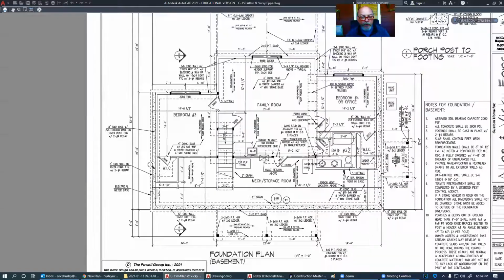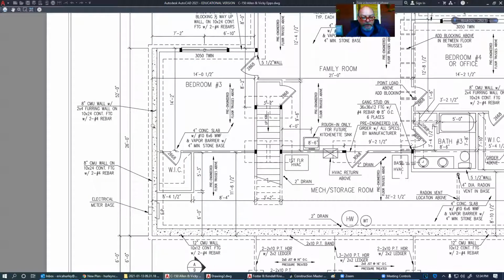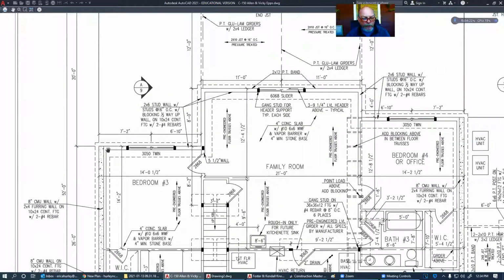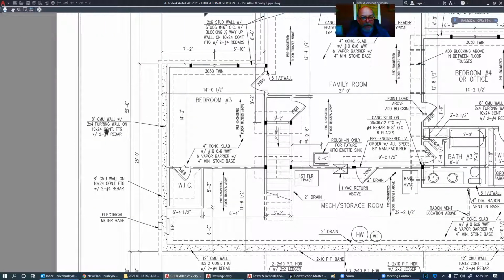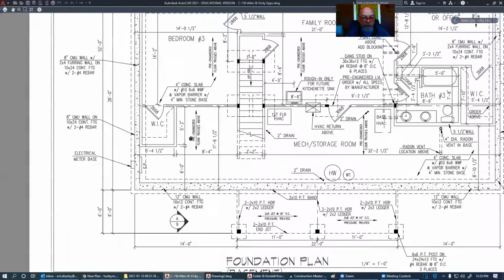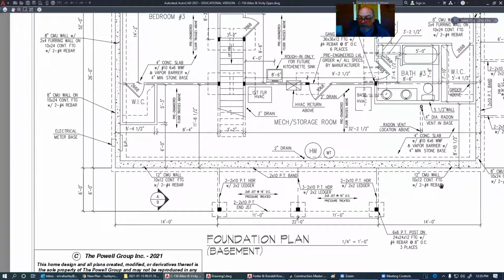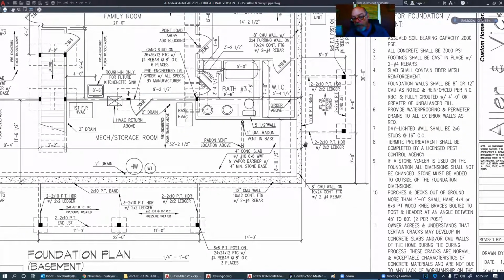Okay, so if we're looking at this drawing, we see that this is concrete across through here. But then look up here at the top. Now all of a sudden we've got these walls up here, these daylight walls. Well, there's a great big note that says we have 2x6 stud walls in here, as well as an 8-inch CMU wall down here, a 12-inch CMU wall here. I give the note again over here, just in case he's looking on this corner and wonders what this is. He doesn't have to chase it down. And then I'm telling it it's going to have an 8-inch CMU wall here.